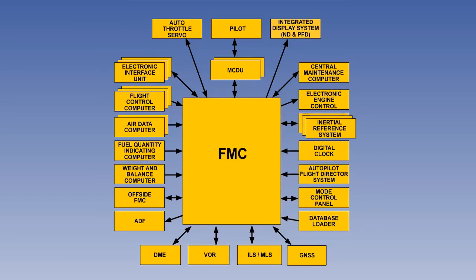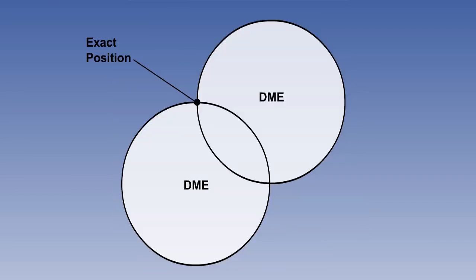In the case of 4D RNAV, the equipment is far more sophisticated than 2D RNAV, and usually takes the form of an integrated flight management system, which we will look at in its own lesson. A full FMS will have IRS and possibly GPS as inputs as well. The information is compared with DME and occasionally VOR-DME in order to calculate a most probable position.